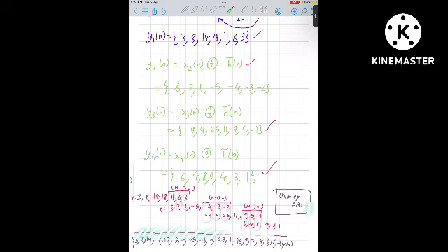So what we have done in overlap add is break the data into chunks of length L. Our filter is of length m, and then in order to do the proper convolution or the multiplication in the frequency domain, we append them with zeros. All these blocks of length L are appended by m minus 1 zeros, as you can see over here, to form them of length m. Similarly, h tilde of n is of length m, so we append them by L minus 1 zeros.